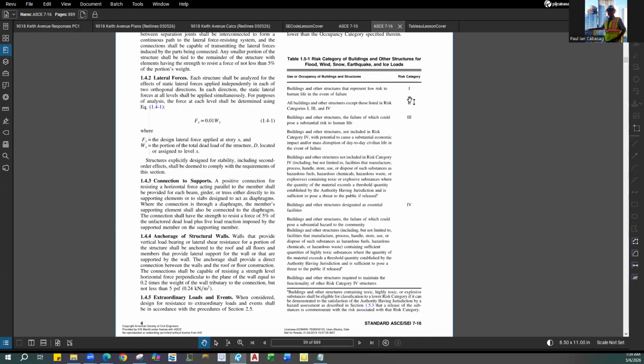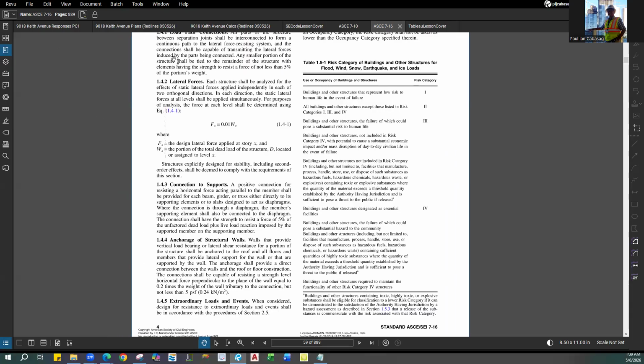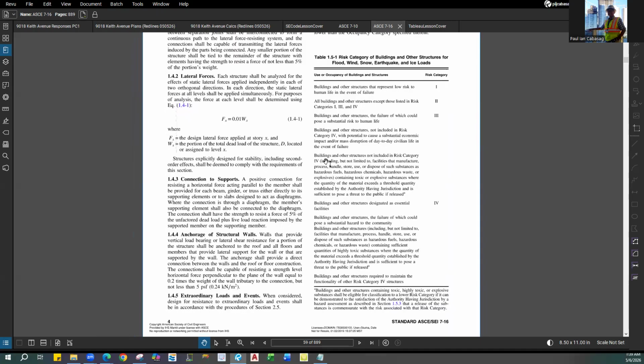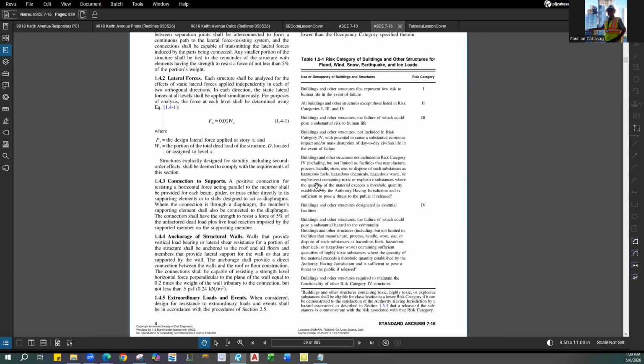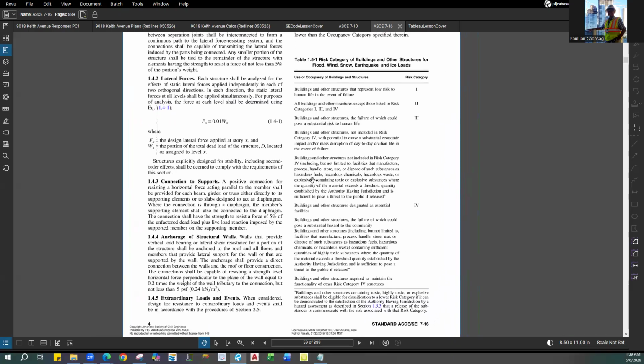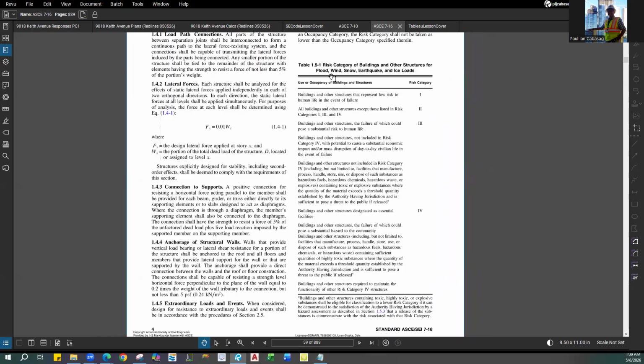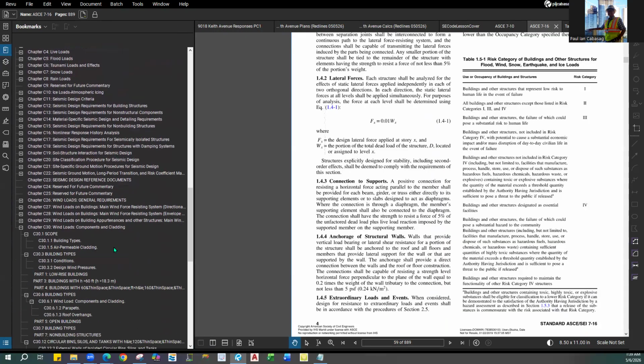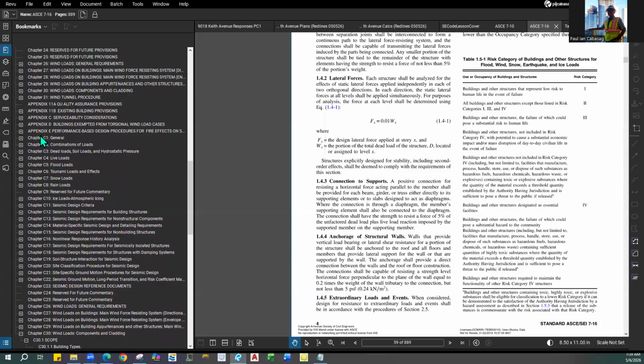And if there's one that's more of a gray area, I would probably refer to the commentary. So a lot of these building codes have it either at the end or right next to it, if you're using something like the TMS masonry code or an ASCE concrete building code. Those will have it side by side with the actual code and then the commentary. But for this ASCE 7 code, it's mainly at the end. So if you look here, it's designated as C. It's one of the appendices, or after the appendices.